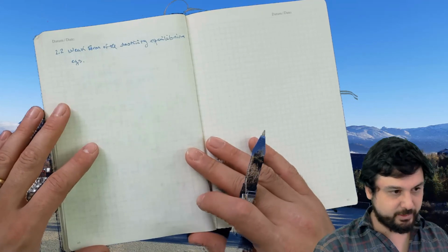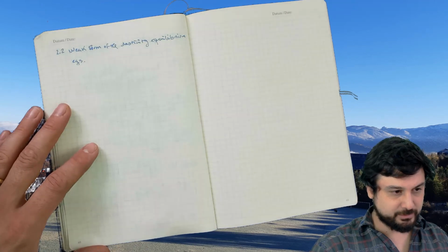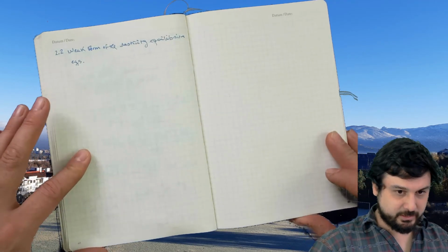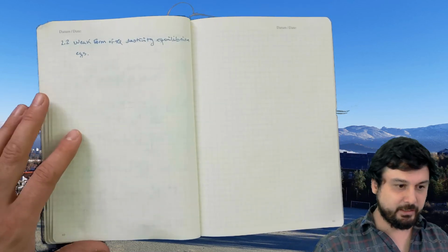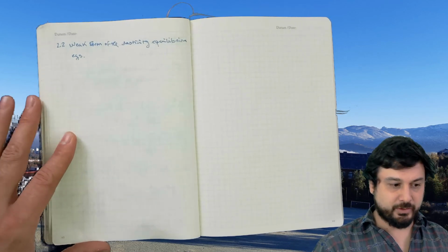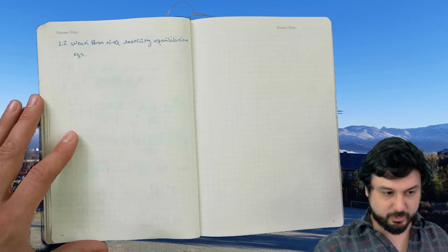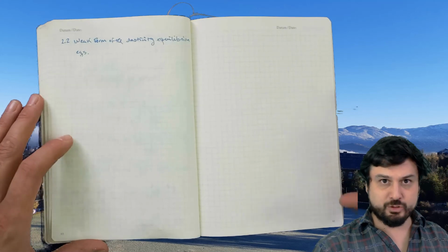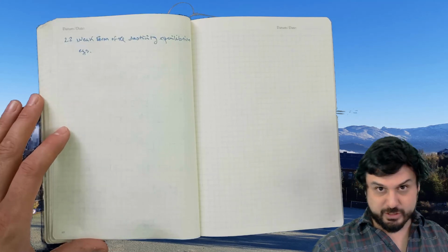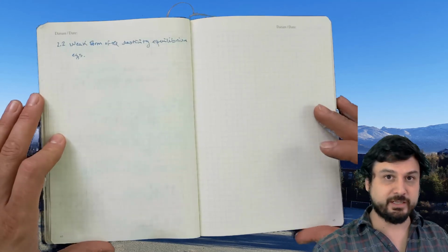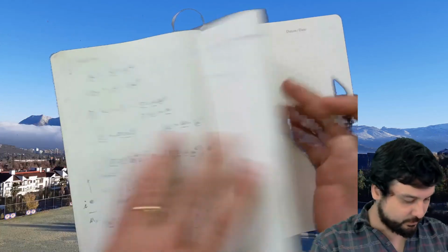So what is the weak form? The weak form is also known as the variational form of the equation. And in this case, there's two ways to go about it. One way is, for any PDE, for any partial differential equation, there's a specific set of procedures you can apply to the equations to turn them into a weak formulation. In this case, I want to give the more intuitive notion using the principle of virtual work. Okay, so the principle of virtual work is just another way to state equilibrium.